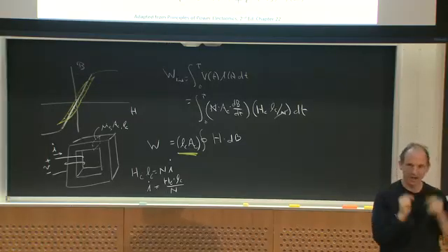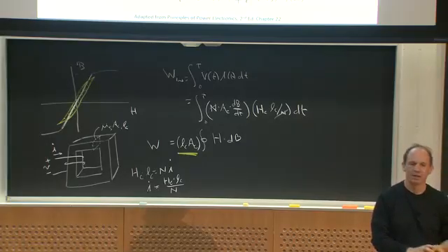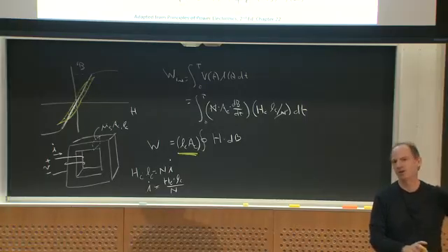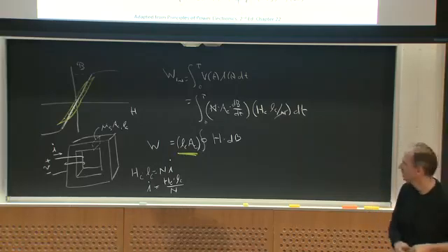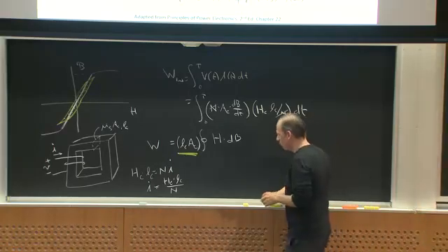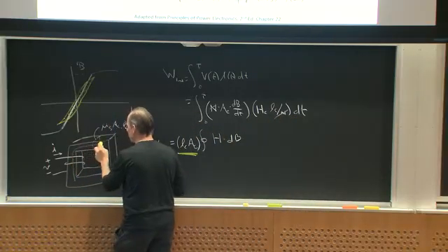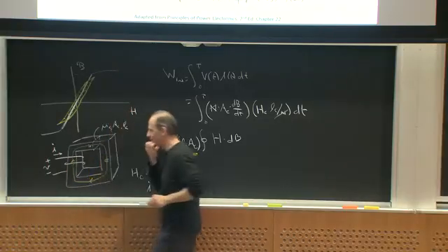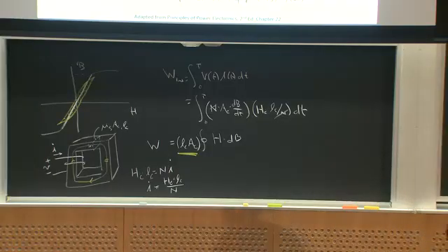I should say that this kind of loss under the magnetic domains is one form of loss you can get. There are other forms of loss you can get, however, in cores that are not so-called hysteresis or related loss. And one of those is, in fact, eddy current loss in the core. Think about this. What is this core doing? If I put a current in here, I'm putting a flux and a flux density of B through the core itself, right? Well, at low frequencies especially, we often use conductive magnetic materials, right? We use like steel. Steel's pretty conductive.